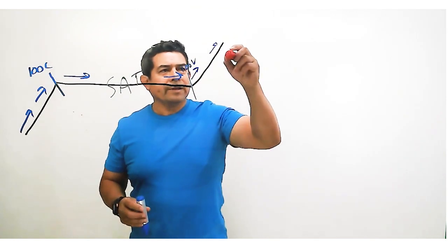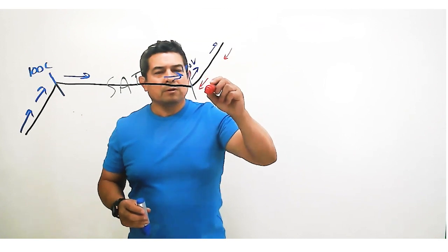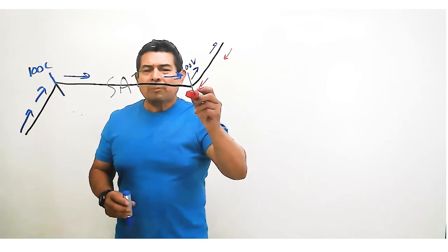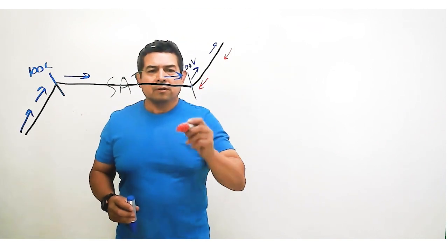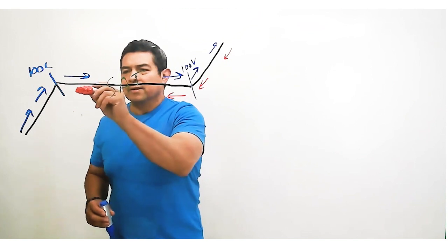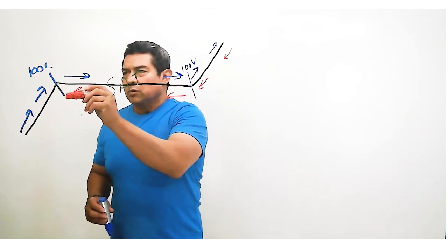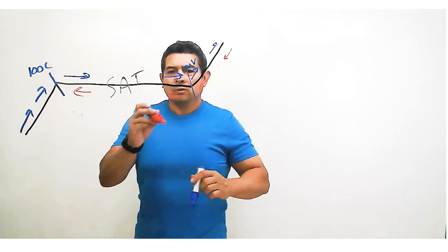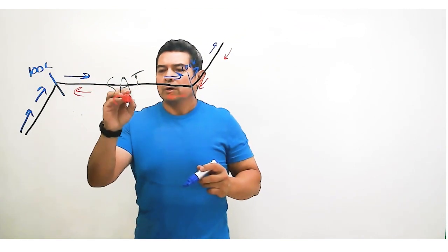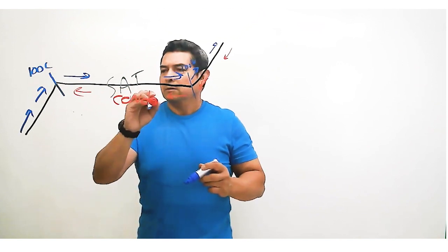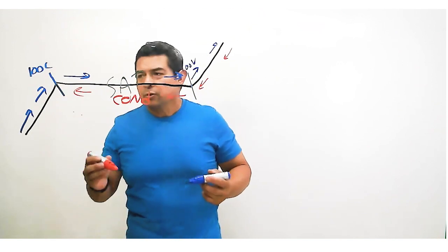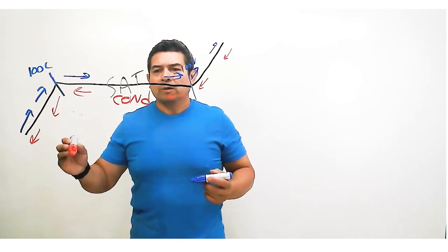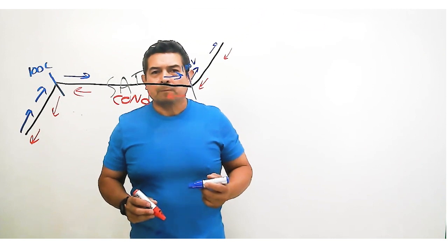Then after we do that, we're going to drop the temperature like this. Once we drop the temperature, we drop it down to saturation temperature. Then we're coming back this way. So now we're going to go from 100% vapor down to 100% liquid. In other words, we are condensing, let's say, the refrigerant. Then we come down like this, and again, we lower the temperature below the saturation temperature.